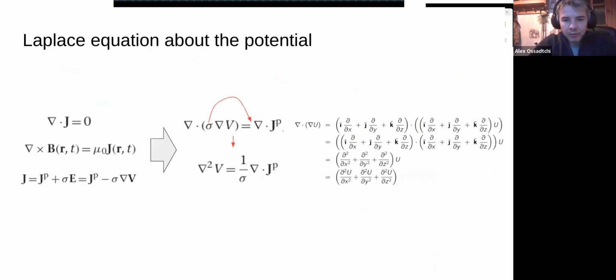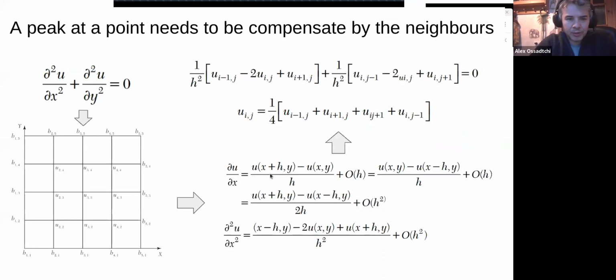And another thing, if we go to the more compact equation like this, then we can say that at some locations in our grid we might have primary currents, and then our equation will be almost the same, except that we have this constant that is changing this relation. So we will have not equal to 0, but equal to the strength, if you will, of our current source. Then you simply create a set of equations for each of the potential values on your grid and solve it.